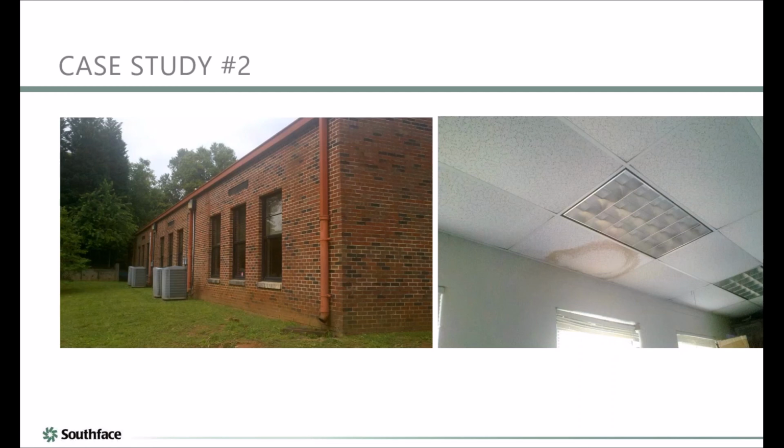Again, we're using a plenum space as a return. The outside air was ducted through that. It had issues with air leaking in, hitting a cold surface, and you could absolutely see it right there. So when the weather conditions are right, let's say it's October and you get some of those first cold nights where there's still a fair amount of humidity in the building, but you start bringing in outside air and it's cold. So that duct is cold. So all the humidity around it, that outside air duct is above that drop ceiling tile. Right. It dripped and dripped and dripped. And you can see the sagging of the other tiles too.